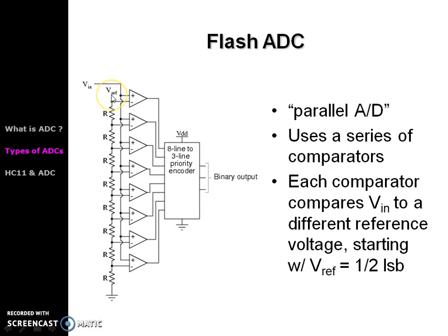When the reference voltage is applied, due to the voltage divider network, some standard values of voltage as per the values of resistance exist at each comparator's inverting terminal, so different voltages exist at all the inverting terminals of the operational amplifiers.